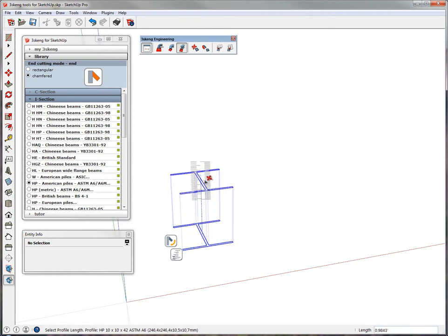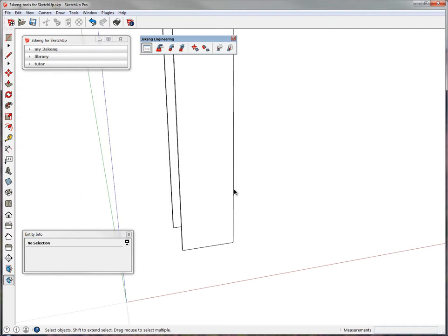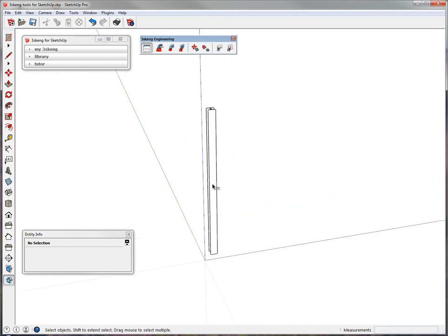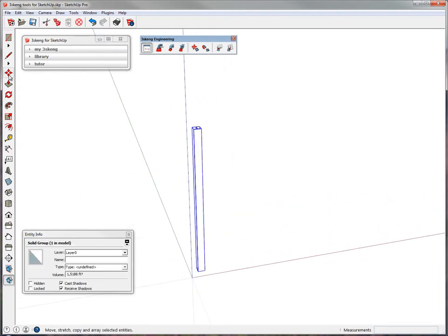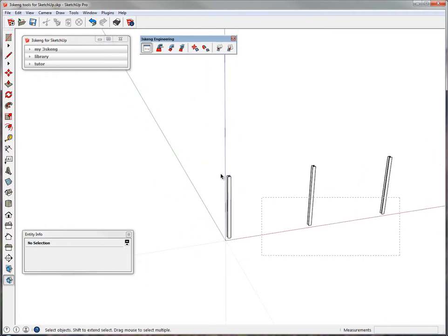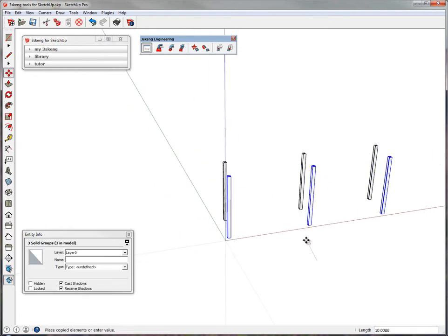By clicking, we can now decide what height we want to have. On the small scale you see, the right side gives you a metric indication and the left side imperial. You can of course also input the length with your keyboard, which we will do in this case. As our 3skeng tools integrate seamlessly in SketchUp, we make use of the SketchUp copy functions if we want to duplicate our steelwork beams.